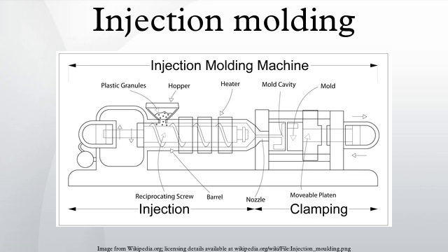Some molds allow previously molded parts to be reinserted to allow a new plastic layer to form around the first part. This is often referred to as overmolding. This system can allow for production of one-piece tires and wheels.